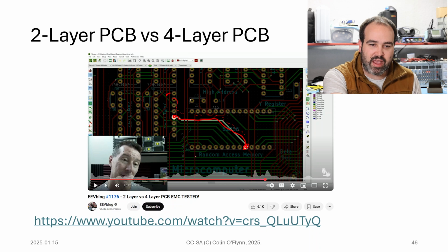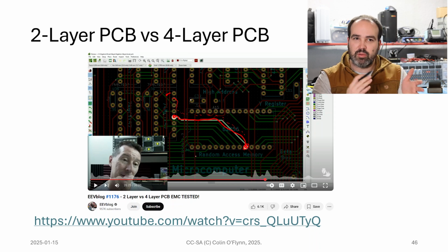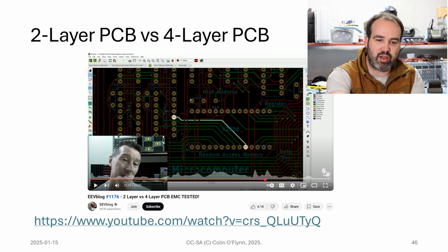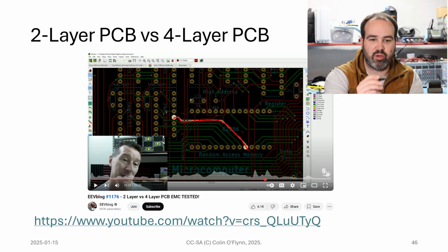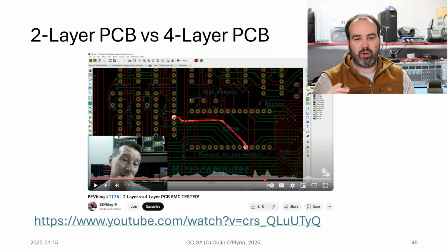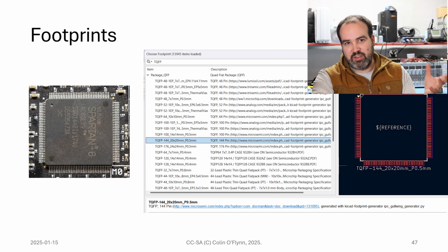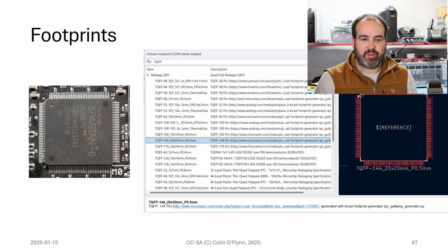The bottom layer now has all these other traces. There's only the 2 layers, so it's very limited. When you go to 4 layers, you have ground everywhere, so hopefully the return current most of the time can flow right under the trace. Everything works really well. So these get into way more advanced topics, but it's good to know about it when you're starting out even.